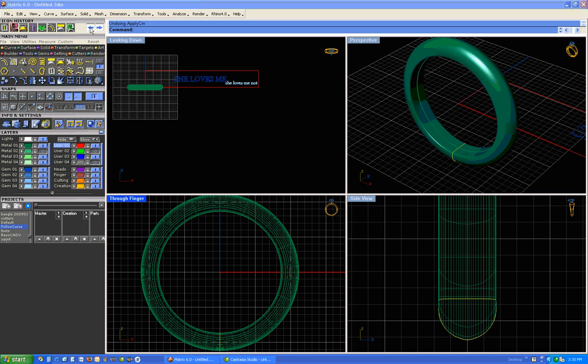A better way to do this is to highlight both the font curves and the rectangle created by UV Curves. And I'm going to go ahead and grab all of them. When we apply both back onto the surface together, the text remains proportional to the Create UV Curves rectangle, and the rectangle is draped back where it came from. This means we now have a set of curves that define the edges and ends of the extracted surface. You'll probably want to delete these before doing anything else. Be careful not to delete the ring rail.